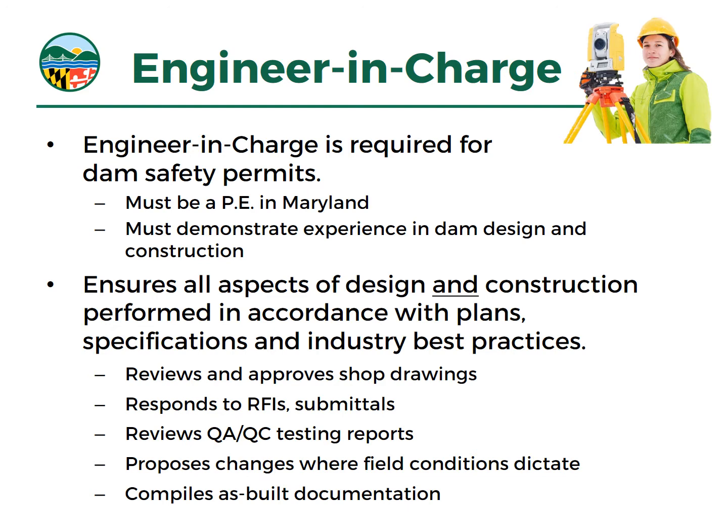So that person might review and approve shop drawings or submittals. They'll review quality control testing reports, and they can assist during construction. If there are changes in field conditions, they propose changes that may need to be reviewed by the permitting authority to accept or modify a permit, and then they'll compile the as-built documentation.